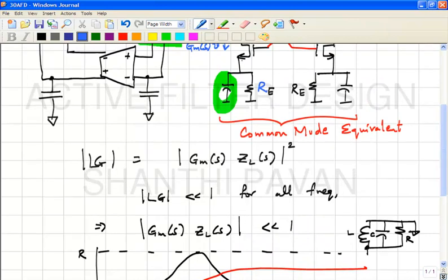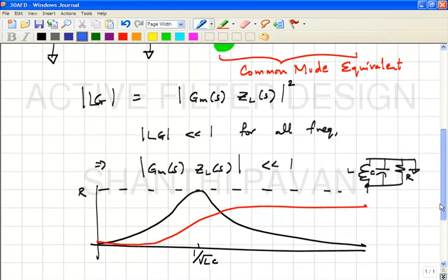At infinite frequency it must tend to gm of the transistor, because the capacitor becomes a short. Is that clear? So, it must start from 0, do this, and then eventually go back to saturated gm. Is that clear? Okay. So, which do you think is the problematic region?